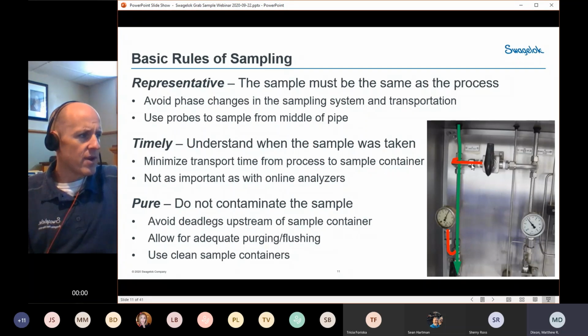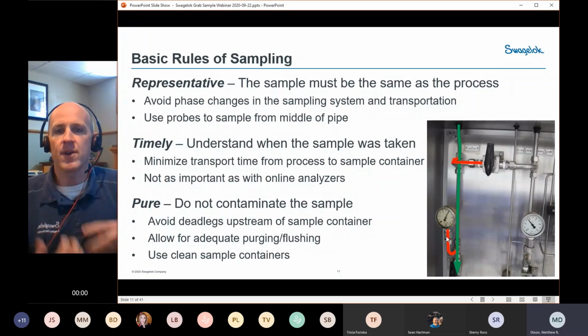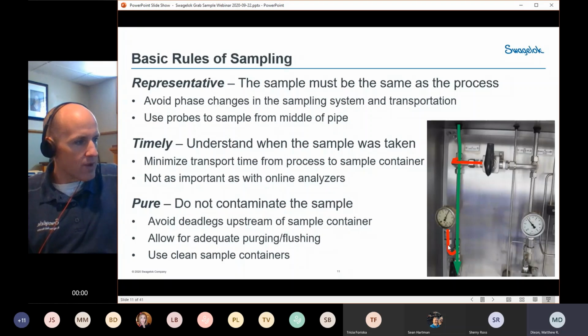Well, those 2 T's have these branches here in red that filled up with fluid at some point during the process. But how old is that fluid? There's no flow in this, right? So there's nothing flushing through and flushing out this old fluid. And as this new fluid is going past, molecules are coming out of this branch and just slowly contaminating that stream as it goes by.